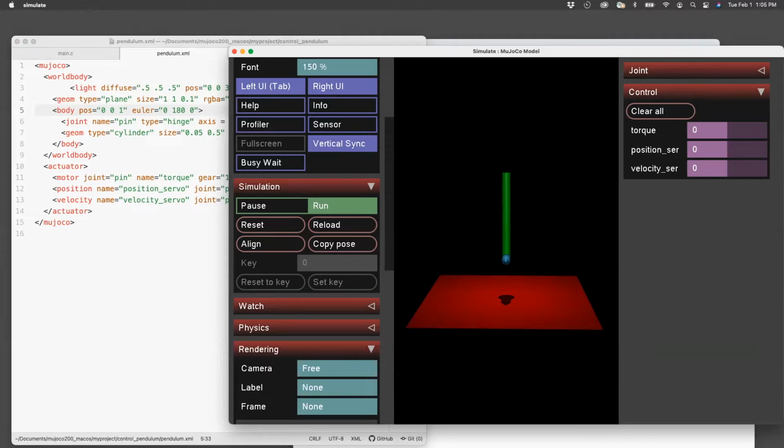If you want to check the dynamics, then you probably want to tilt it by an angle, and we'll do that using the code. Now you can actually change the set point for the position servo. So for example, if you wanted 30 degrees, this is to the right. So positive is to the right, counterclockwise. And then that's negative. Here what's happening is I'm just changing the set point, and then the PD control, because there's a P, there's a D, is actually taking care of ensuring that the angle is maintained. Okay, and so you can drop that down.